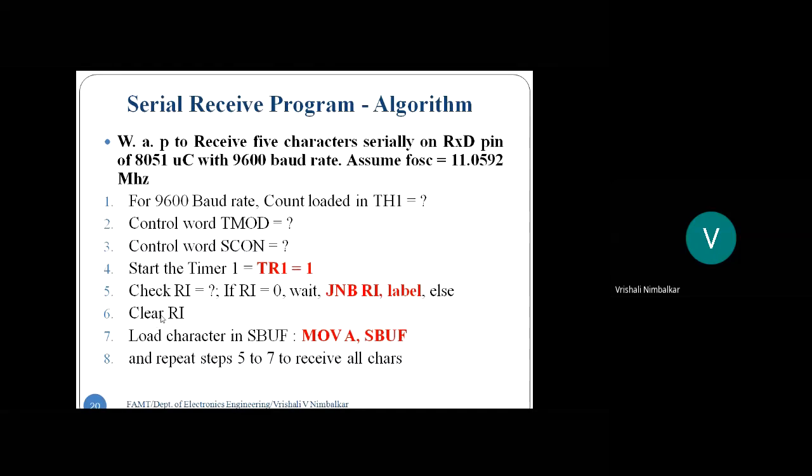Now see here, students, whenever the reception begins, the bits are received by the microcontroller on the RxD pin, 1 bit by 1 bit. Whenever 1 bit is received, it does not directly get loaded in the SBUF register. When the bit is received, it is first kept in a temporary shift register. There is one 8-bit shift register internally.